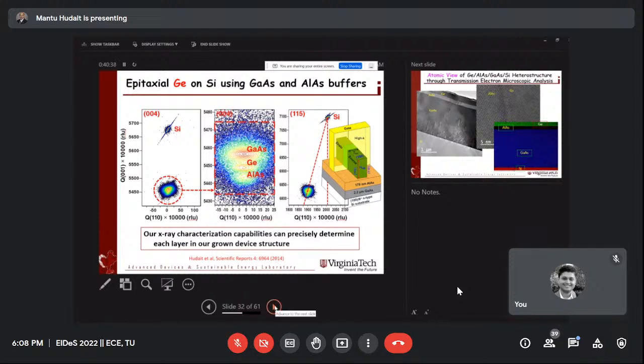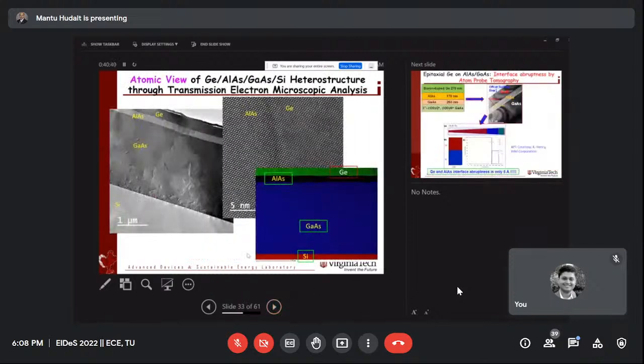I'll show you the materials. That's the stack that my student did. He left to Georgia Tech for the TM. This is the gallium arsenide grown on silicon. Aluminum arsenide, I can tell you why it is aluminum arsenide. We put germanium on the top. That is basically the fin. You know the GOI, people talk about the SOI wafer, the silicon on oxide on silicon, or germanium on oxide on silicon, think about that. The oxide is the large band gap.